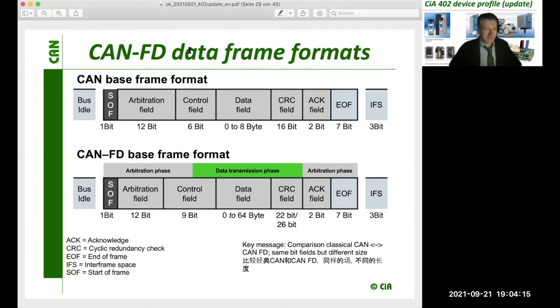There are some nasty side effects, physical effects, occurring because of it, so we had to fix certain issues. There are companies developing various methods to reduce parasitic effects of the higher speed. For CAN FD, for the moment, the maximum speed is 4 to 5 megabit.